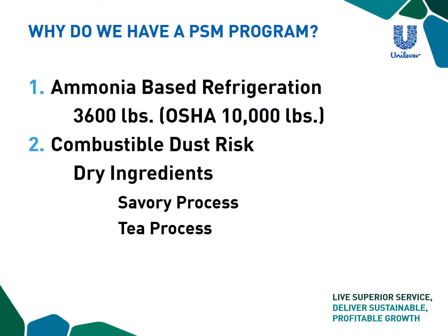So why does Unilever Independence even have a PSM program? Well, first, it's because we have an ammonia-based refrigeration system on site that contains 3,600 pounds of anhydrous ammonia. While OSHA sets the standard at 10,000 pounds as a threshold to have a PSM program, Unilever takes an extra step and mandates that we follow the OSHA PSM standard even though we have a smaller system. This is good in and of itself because it makes us follow these guidelines and the framework that keeps everyone safe as well as our community.